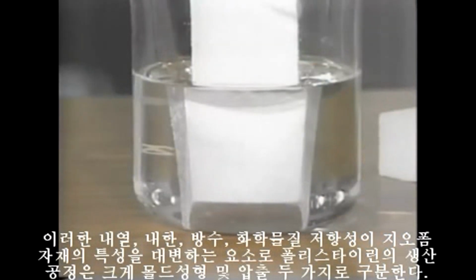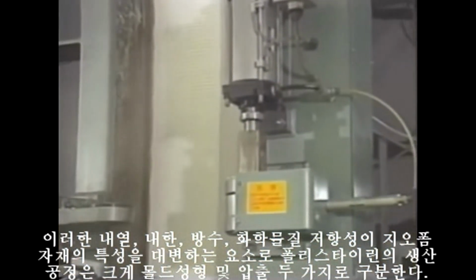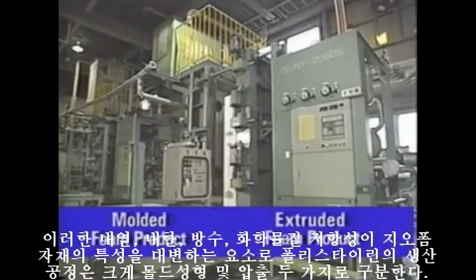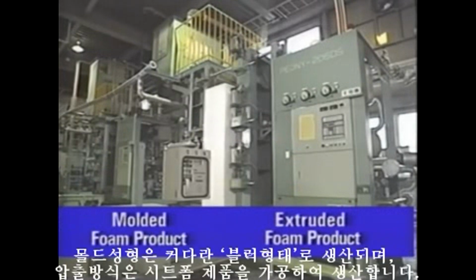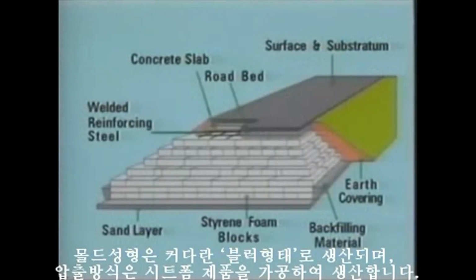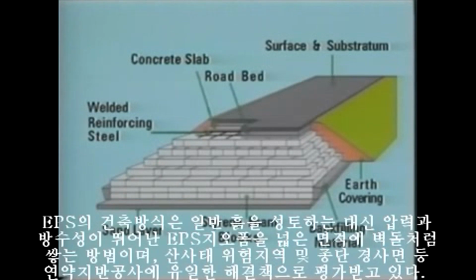There are two methods for manufacturing expanded polystyrene: the molded foam method, where blocks of foam are produced, and the extruded foam method, which produces sheets of foam. In the EPS construction method, very large lightweight molded foam blocks with excellent compressive strength and water-resistant properties are stacked upon each other as ground fill material.